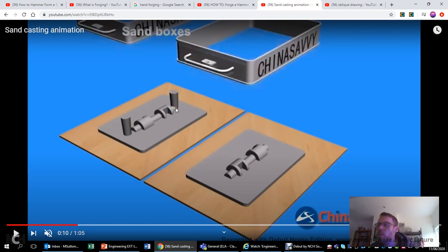Those are going to be where the actual molten metal flows in. You'll see what I mean and how it's done in a minute, but you obviously have to have somewhere where the metal can flow in, and potentially you always have to have two so that the air can escape from another place. And the placement of this is very important so that air can escape, because if air becomes locked inside the mould, you'll get a bubble of superheated air or gas, which means that the metal won't flow into that particular point, or it won't be as nice a casting as it could be.